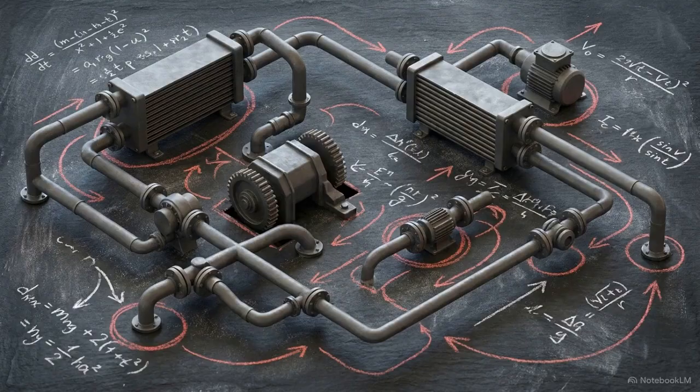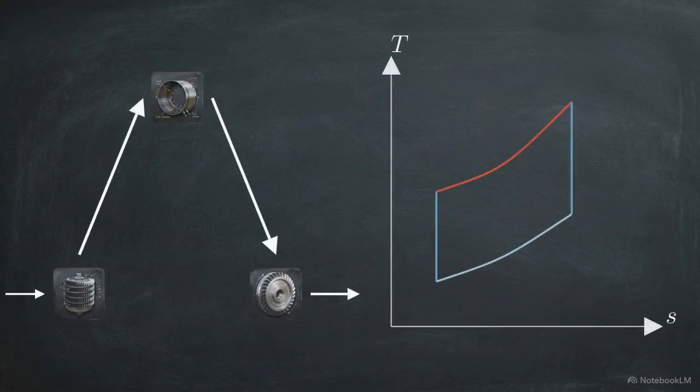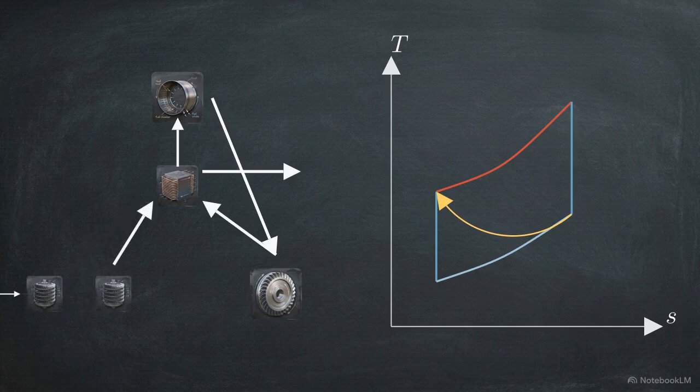that lost efficiency. When the goal is stationary power generation, engineers deploy 3 specific modifications to maximize rotational shaft work over all else. The first method is regeneration. Instead of venting exhaust out of a stack, a heat exchanger captures wasted thermal energy to preheat incoming air. By transferring enthalpy back into the system, the combustor requires significantly less fuel to reach its target temperature.